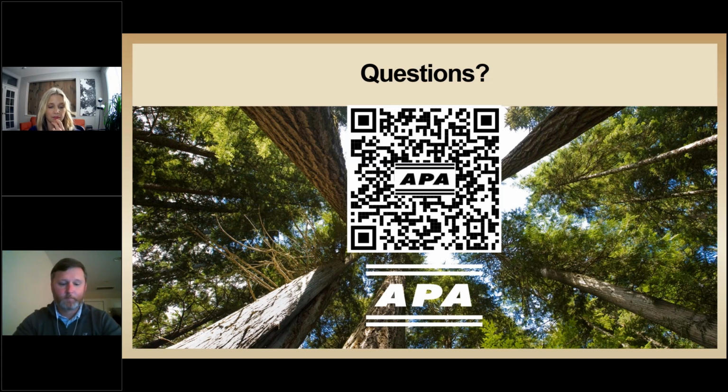And then another very common question we get at APA, and it came in today, was: they're used to specifying CDX, so why do we discourage that? Yeah, CDX is a common construction term, but if you specify CDX and you get material that actually meets the specification, you're going to be limited. A lot of people use CDX when they just mean sheathing, just wall sheathing. They may not even mean plywood or OSB specifically. But if you specify that, you're limited to a plywood panel, so no OSB, and you're limited to a C face and a D back, because that's what you specified.